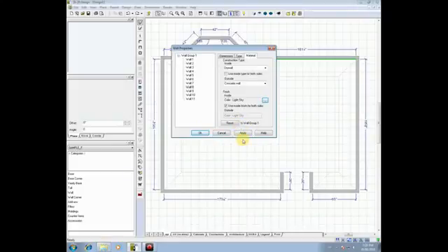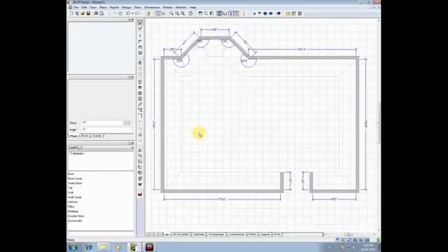Why have I been doing that? Well, it's interesting because in Windows, if you choose Apply, Apply saves but leaves the menu open so you can continue to make changes. In this quickly, I've changed the dimension of a wall, I've changed the height of 3 walls, I've even made a wall blue. When I'm finished, I'll click OK, which means confirm my selections but close the menu.